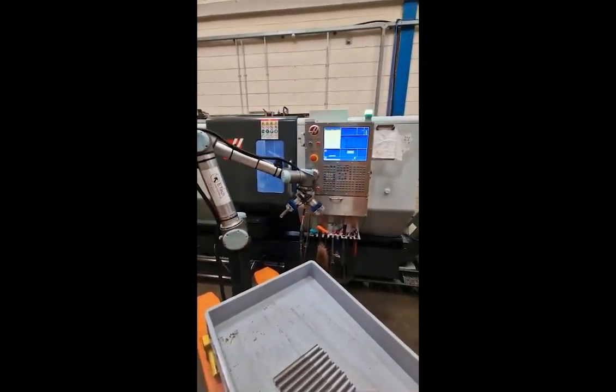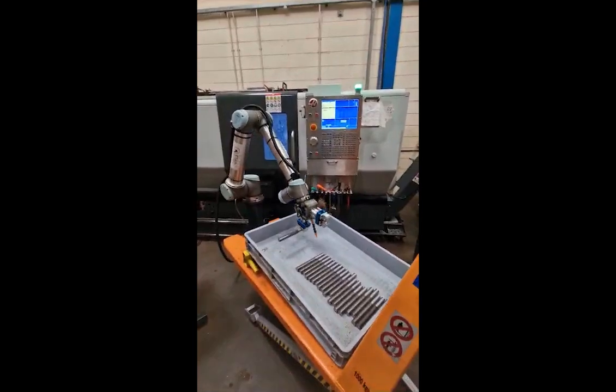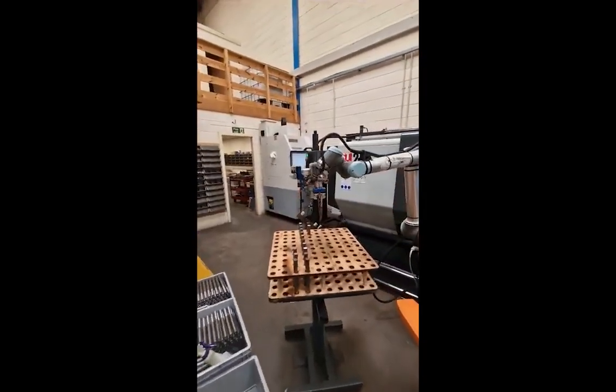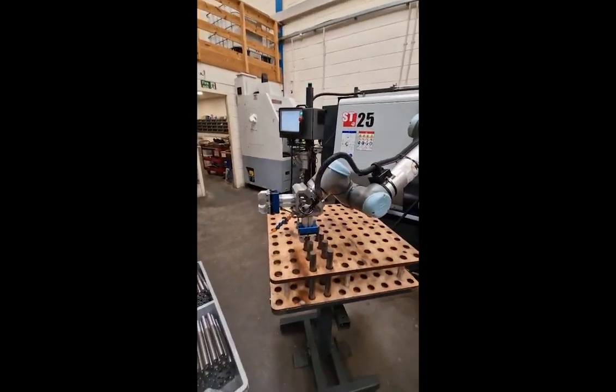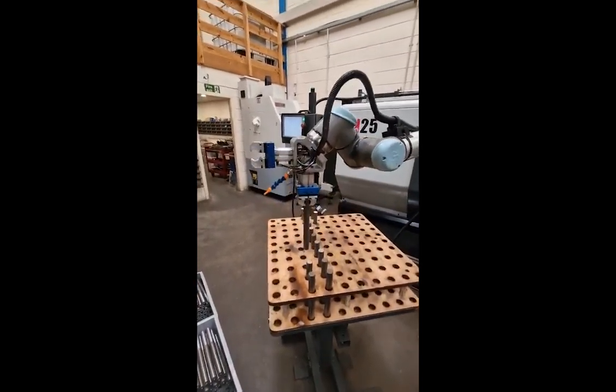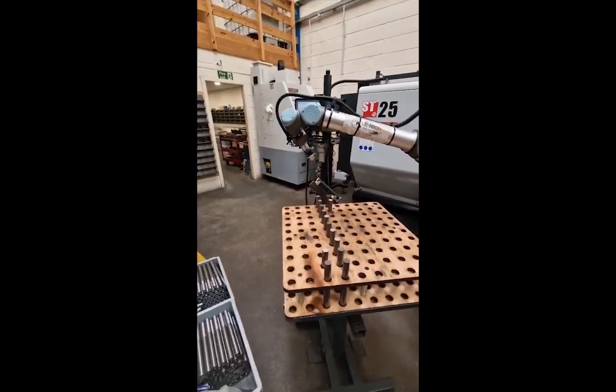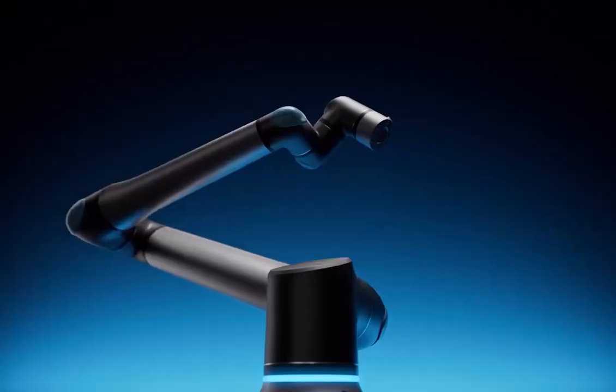The robot will exit from the machine, and on the wrist of the robot there is a small button that forms a thumb. It'll press the start button and that will start the machine. It'll exit and then drop the finished part into a tote and go to the loading table to pick up the next raw part.